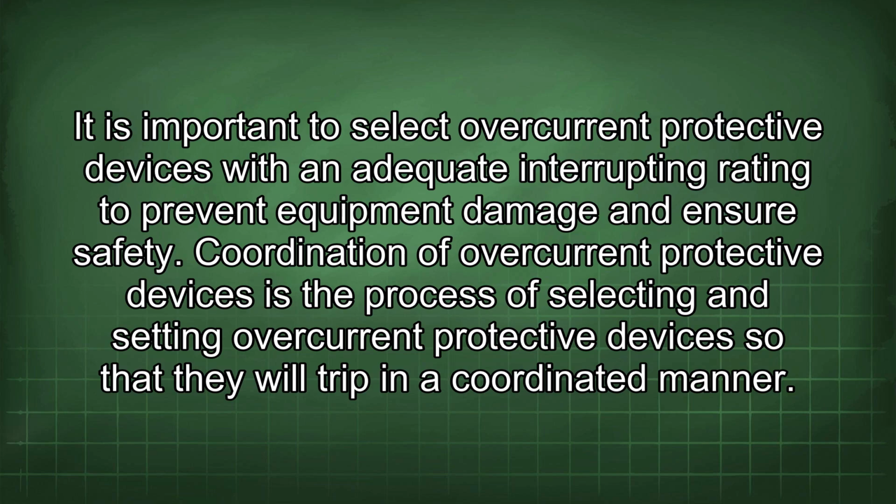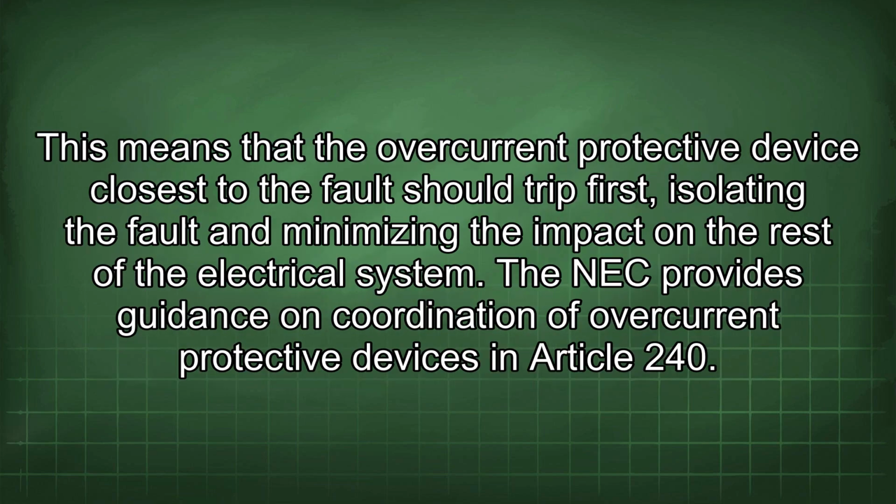Coordination of overcurrent protective devices is the process of selecting and setting overcurrent protective devices so that they will trip in a coordinated manner. This means that the overcurrent protective device closest to the fault should trip first, isolating the fault and minimizing the impact on the rest of the electrical system. The NEC provides guidance on coordination of overcurrent protective devices in Article 240.